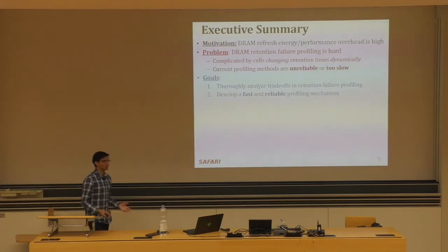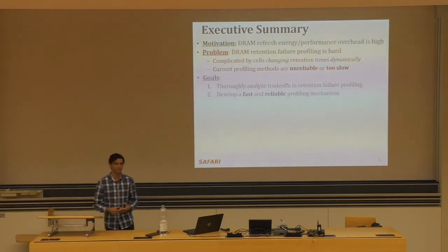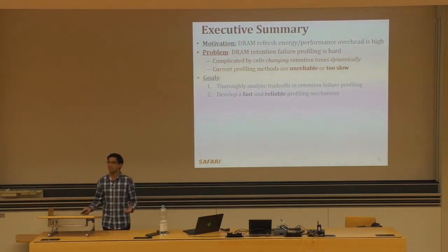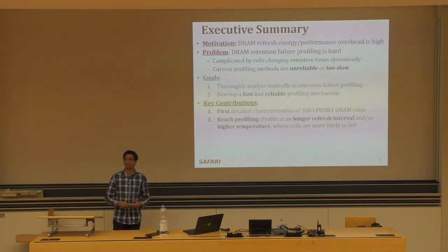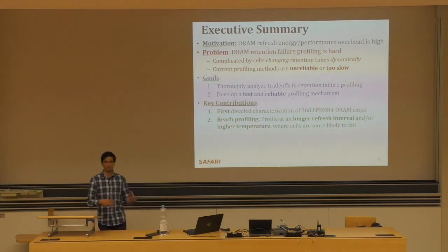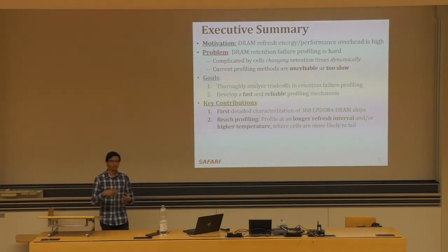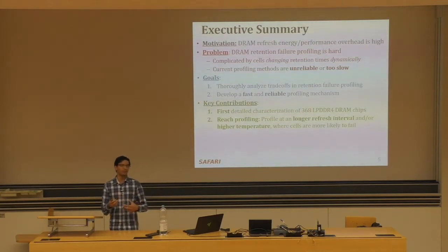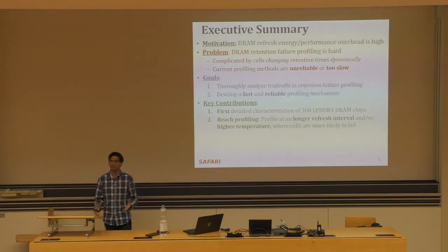And therefore, our goals in this work are twofold. First, we want to thoroughly analyze the trade-offs surrounding retention failure profiling. And second, we want to use what we learned to develop a fast and reliable profiling mechanism. And to this end, we make two key contributions in this work. First, we perform the first detailed characterization of LPDDR4 DRAM devices, and we use what we learned from that study to propose reach profiling, whose key idea is to profile at either a longer refresh interval or at a higher temperature than the target operating conditions.